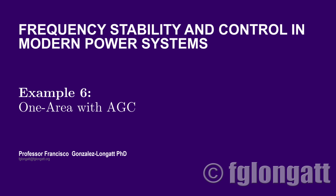Well, this is the end of this video. I would like to say thank you to all my students in frequency stability and controlling modern power system. This is all for example number 6. In this example, we created a single area control system, including the primary frequency control, the turbine dynamic and governor, and in this very specific video, we added a secondary frequency control loop, that is the AGC, the automatic generation controller.